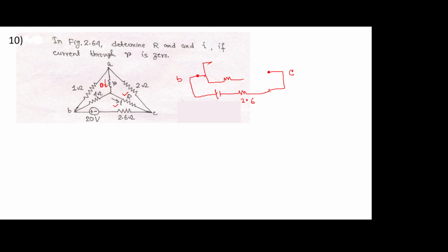So this is one of the resistances given, this is another, it is connected via C. Now another branch, which has a resistance of small r, it is given that no current is flowing through it. Since no current is flowing through it, this acts as an open circuit, and we can very well remove this branch, right? So let's get rid of this branch. Then this is given as 1 ohm, this is given as 2 ohm, this is 4, and this is R.